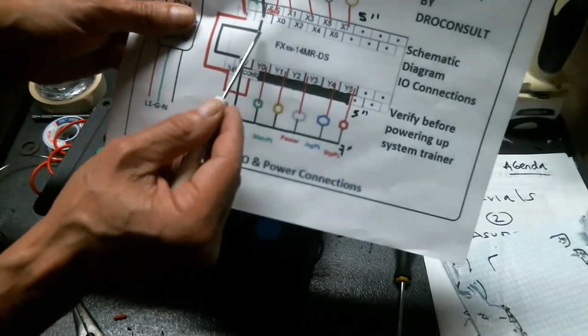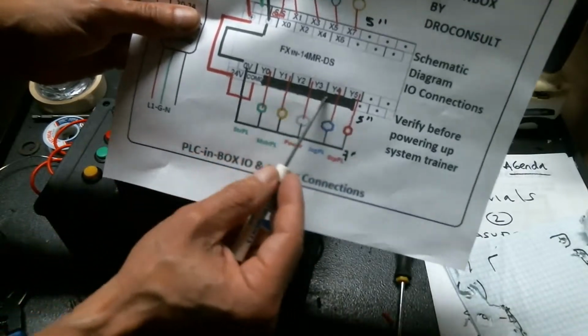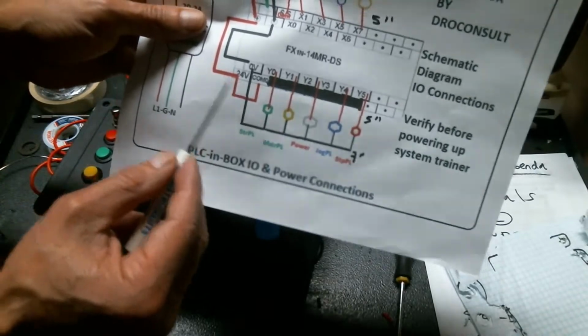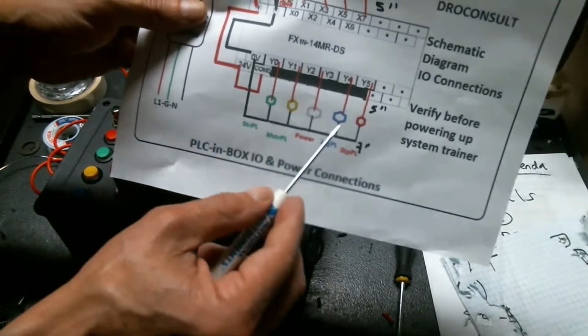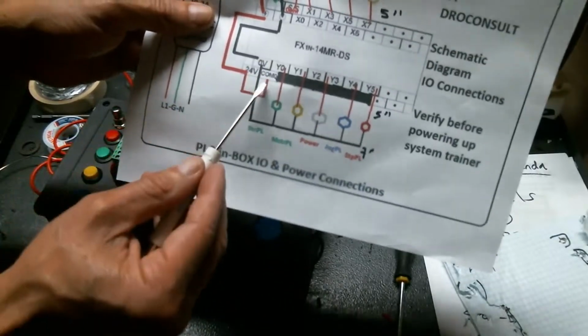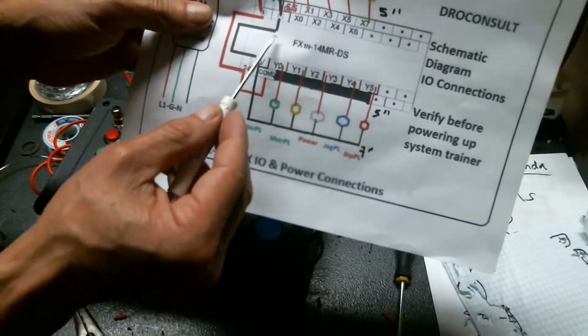Couple of bridges here. I'm gonna bring negative to the other side of the controller and positive to the other side of the controller. If we don't do that, according to the schematic of this controller, we're not gonna be able to power up any outputs, right? So these two wires, which are internal wires, are gonna have to be put in place right here, right?